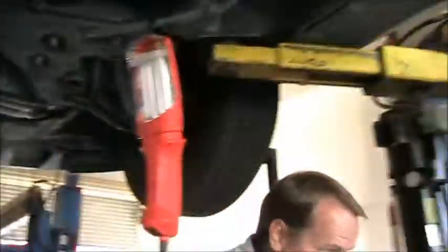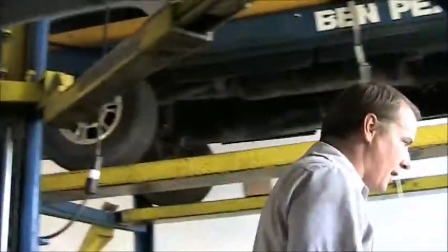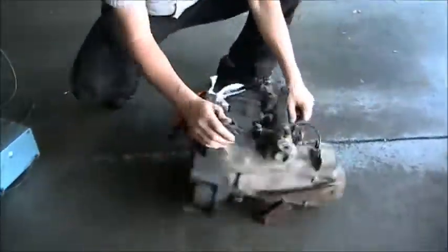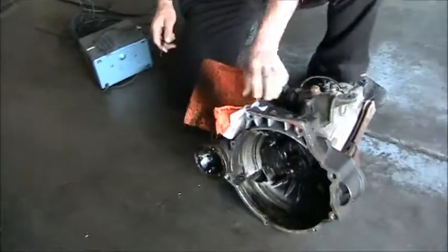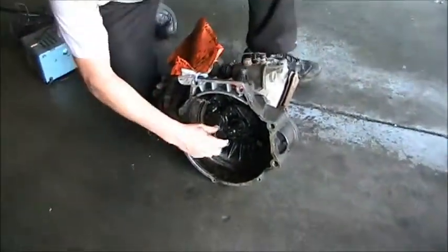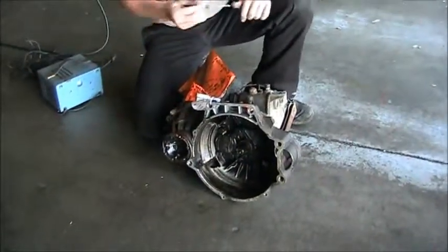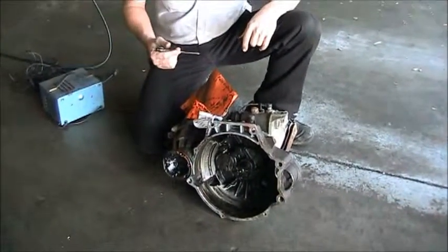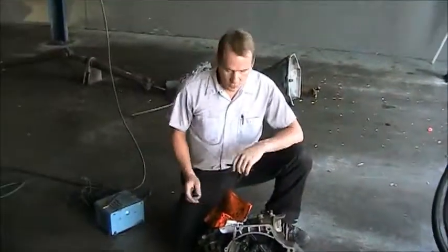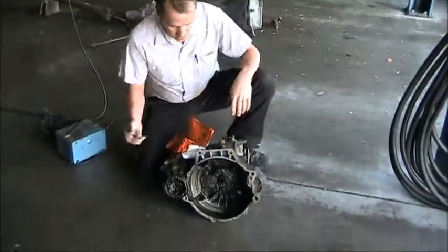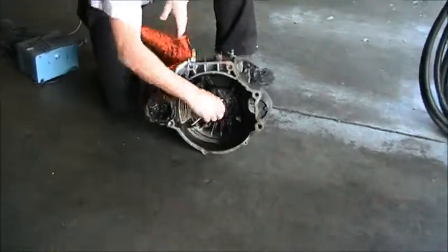It's out of a Volkswagen. I'm going to show you that. This is a used transmission we're going to install. Now, here we have a manual transaxle. So, this is going to be your input shaft. This is connected to a clutch disc. The clutch disc enables you to disengage the engine from the transmission so you can stop and hold the clutch in without moving while your vehicle is in gear, as well as being able to shift it when you depress the clutch. So right now the vehicle's in neutral.